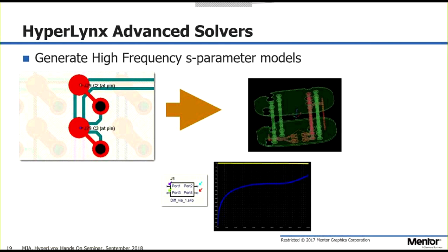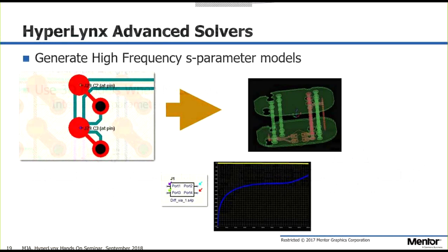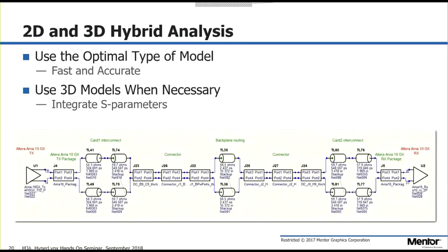Anyway, so that's really going to help out with the accuracy of how things work out. We can take that S-parameter model back and maybe plug it back into LineSim here. So we've got the trace coming along. This is still a package. We've got some routed traces, and then you might have connectors. But anyway, we can put in those S-parameter models for those via structures at different points along the line